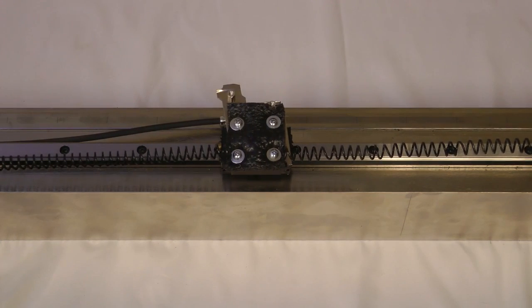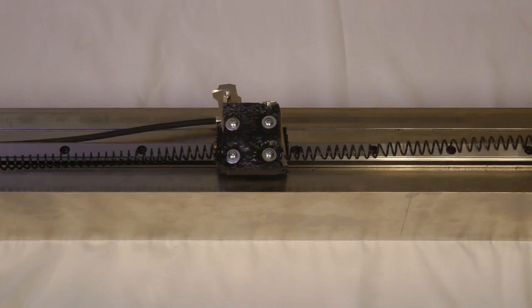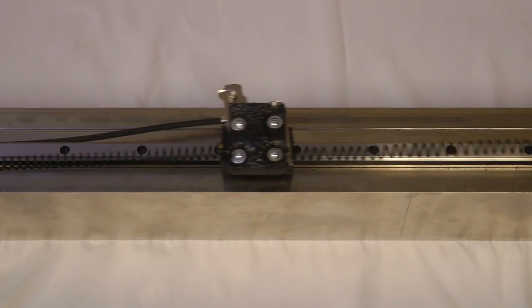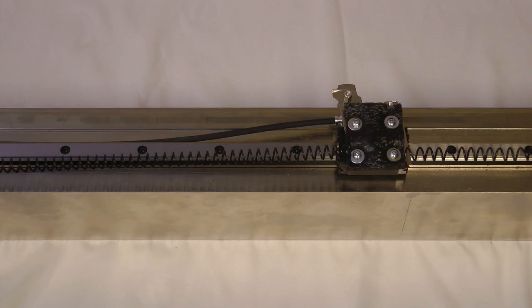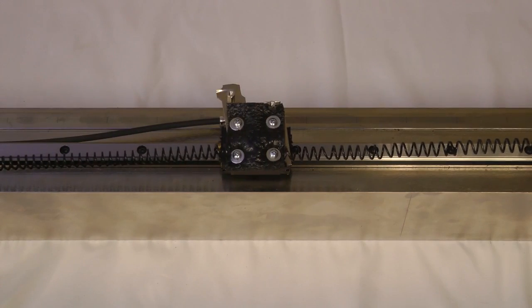As I change the position of the springs, the motor is pushed to a new position. As it moves, it gains momentum, causing it to overshoot and resonate. Systems with high inertia and low friction will show this behavior, as there is little dampening the resonance.